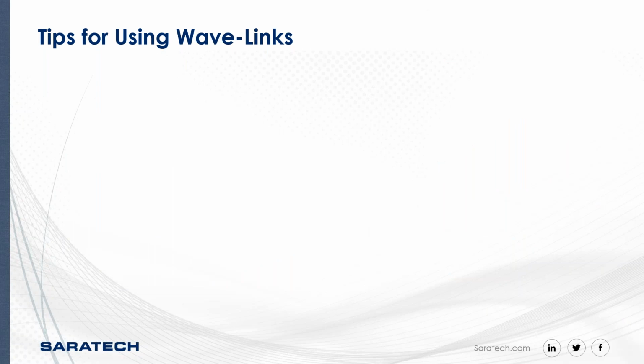Okay, now some quick tips for using wavelengths. If you don't have a plan at the start, it can be very detrimental down the line when you have to manage a lot of different links, broken links, and updates. Especially if you're in an uncontrolled environment and don't have Teamcenter or a PLM system to handle this, it can be a nightmare when you're releasing components. So you want to keep that in mind. Wavelengths should be used in a controlled environment.